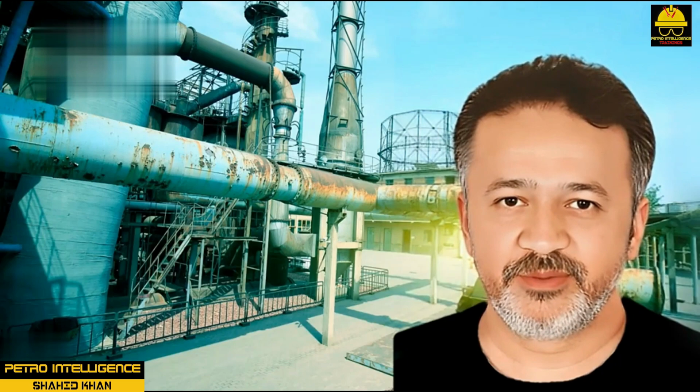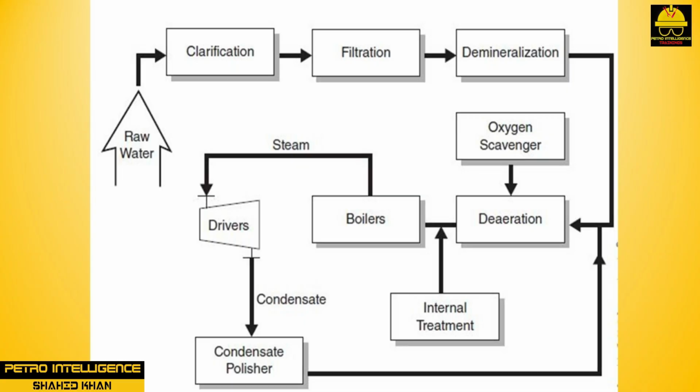Boiler feedwater treatment. Boiler feedwater treatment is the process by which suspended and dissolved solids are removed from the water used in a plant. Clean condensate and demineralized makeup water are deaerated in order to supply boiler feedwater, BFW, to multiple BFW pumps. 2 or 3 pumps are used in the pump-around operation. The primary pump typically has 1 or 2 backup pumps that are placed in standby mode.